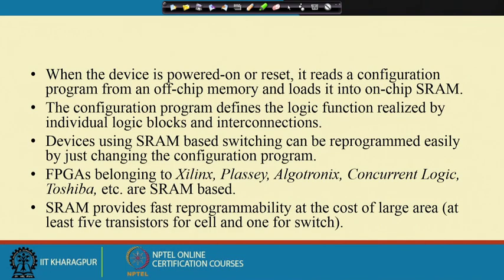Others are also there, so they are also used in many applications. SRAM provides fast reprogrammability at the cost of large area. So, as I said, the reprogrammability becomes very easy, because you can very easily change the configuration program. However, the area occupied is more, because each SRAM bit will require 5 transistors. So, if I have got say 10,000 programmable points, there will be 50,000 transistors just needed